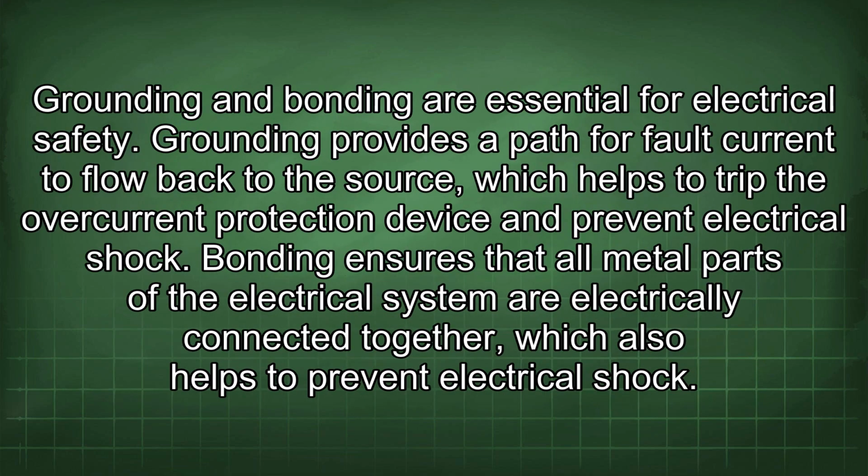Grounding and bonding are essential for electrical safety. Grounding provides a path for fault current to flow back to the source, which helps to trip the overcurrent protection device and prevent electrical shock.